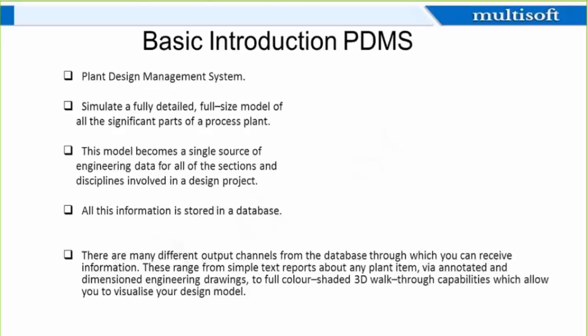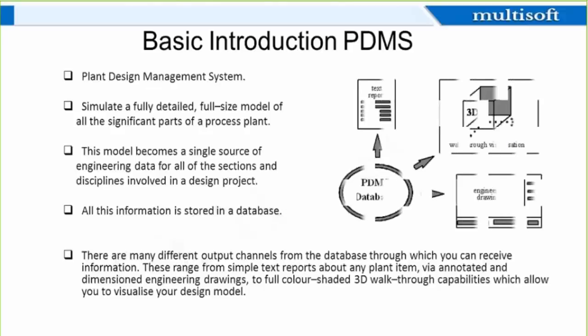And the data stored in these databases can be output through different channels like textual reports, like your MTOs, weight control reports, COG reports, etc., and 2D drawings and review models. Now all the 2D drawings extracted from PDMS are dynamically linked with the 3D model. That is, any change in the 3D model will be automatically updated in the 2D drawing, which basically helps in change management.